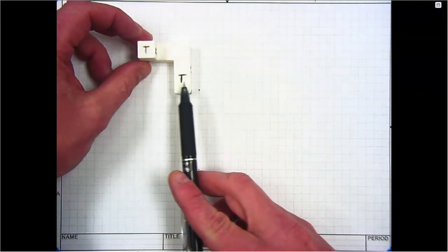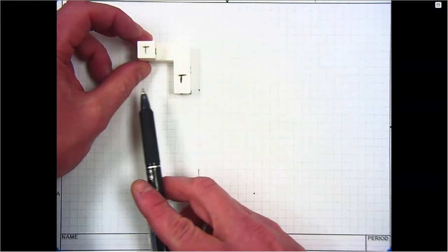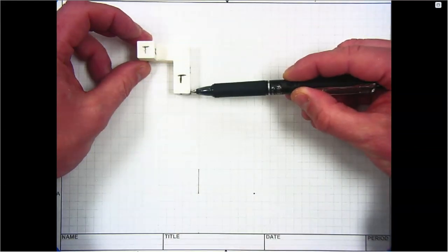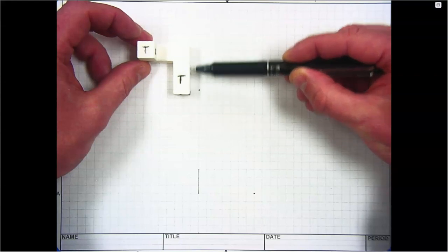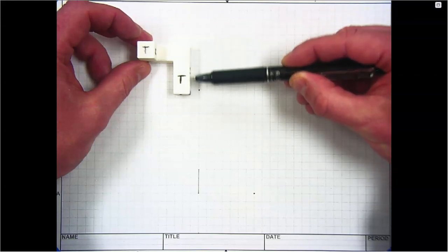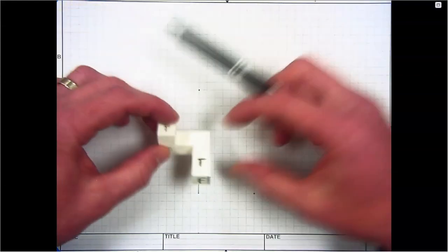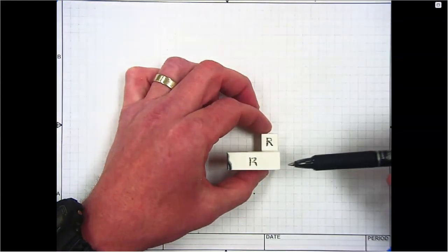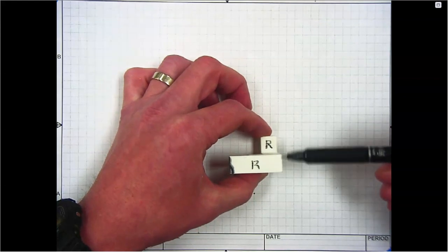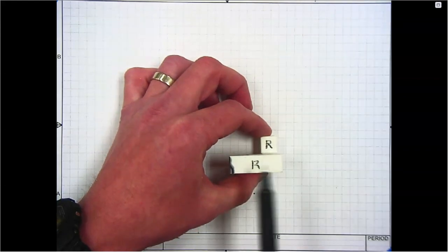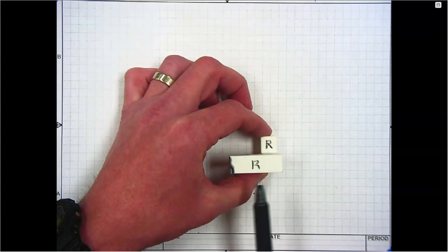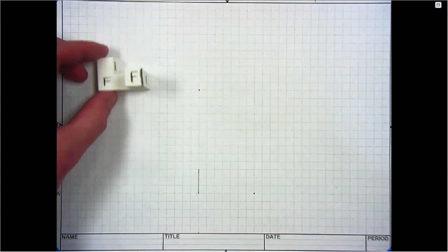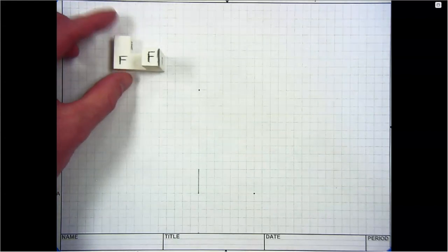We have width again. So width runs from left to right across the top view. And the new dimension we have in the top view is called depth. And so we have depth, and it runs from front to back across the top view. If we move to the right side view, again we have the height dimension, and we also have the depth dimension. And so we'll be using those three different dimensions to draw our sample for our puzzle cube part.